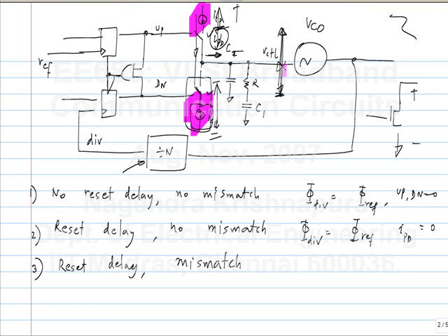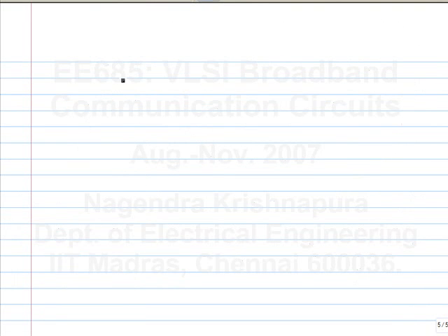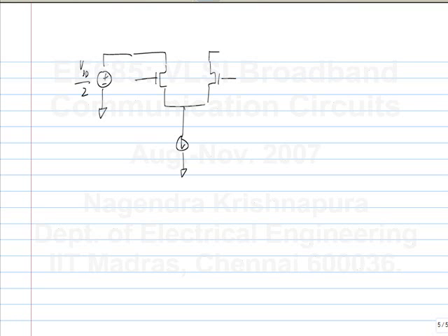In the assignment, I have given you one particular charge pump topology. That is this. I think you are quite familiar with this circuit now. So you want a switch current source. So again, one way to do it was using a differential pair which controls the current. Okay, it steers the current either to the left side or the right side. So let's say the left side is connected to some fixed voltage, half the supply, and the right side is what goes to the loop filter. We have a single-ended loop filter, single-ended control voltage for the VCO. So we can only take one side of this.